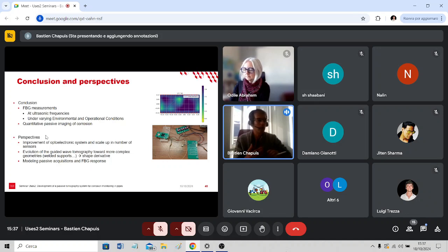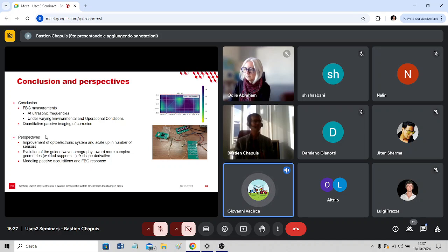That's why all our imaging algorithms are designed to work at a maximum of 50 kilohertz. So if you develop a system that is able to detect waves at 50 kilohertz, we would be very, very happy. Okay, so even if you don't reach 500 kilohertz, it's not a problem. We have application at 40, 50 kilohertz. So supposing to reach 50 kilohertz, after 50 kilohertz, it's better to increase the resolution than the frequency. Do you agree?